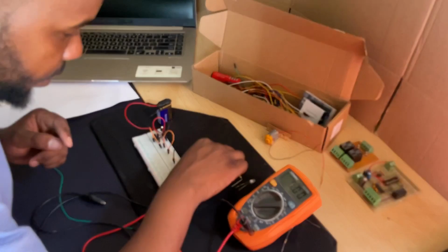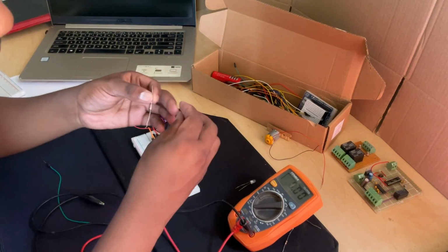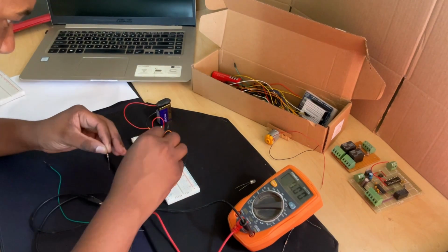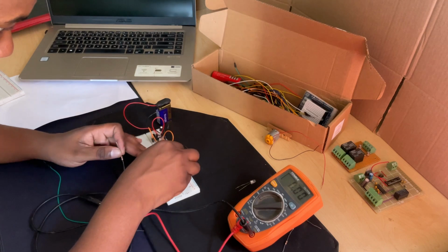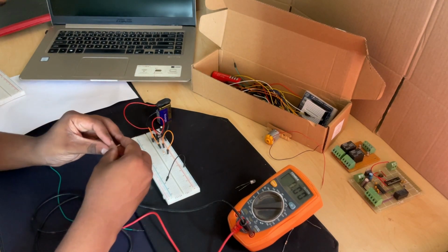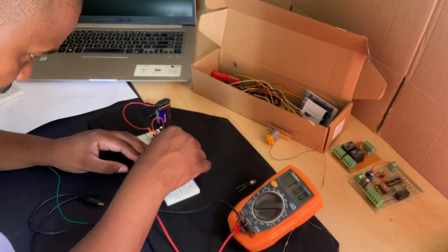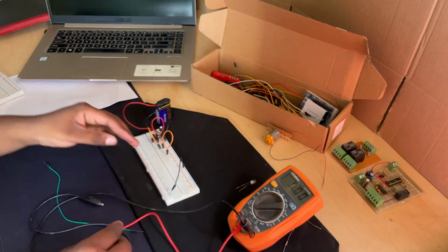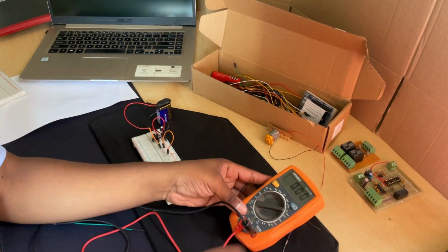This time around we're going to do an additional calculation just to demonstrate the concept. We're going to use two resistors in series of different values. So the first resistor will be 1 kilo ohm and the second will be 2 kilo ohm. So the expectation here is that the 2 kilo ohm resistor will consume twice the voltage that's consumed by the 1 kilo ohm resistor, and we can verify that through our measurements.